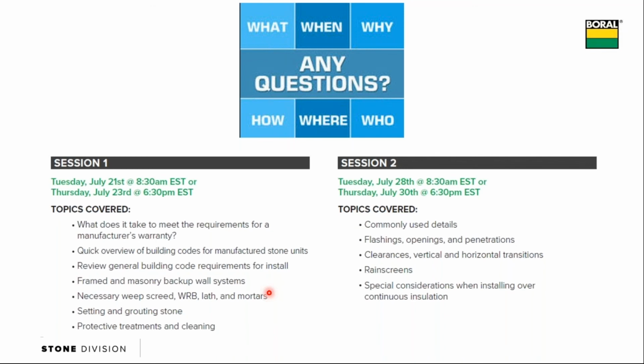So I would say in most cases they do, but the important thing would be that primary to follow the manufacturer's instructions for a primary WRB. Again, that's doing all the heavy lifting. And more often than not, we're seeing those with some requirements around taping, around specific nails and caps and covers, because again, that's what's keeping a lot of the air and water out of that system. So yes, there may be very similar to what we do with the number 15 felt, but I would suggest conferring first with the manufacturer of that product to see how they recommend doing it.